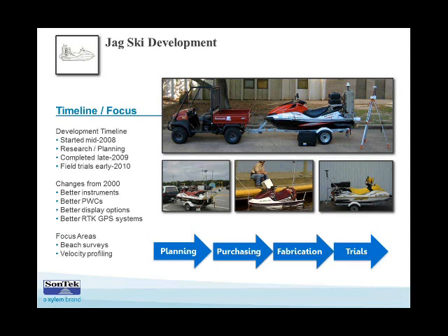The M9, or the HydroSurveyor, does have a pitch and roll sensor, so the depth locations are compensated for pitch and roll, but that's to a point. If you're getting greater than 15, 20 degrees pitch and roll, the M9 is no longer aimed down at the bottom; it's more horizontal. So that could be a limitation if it's very rough.